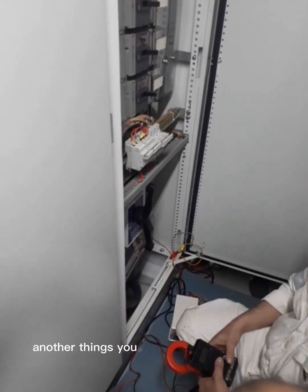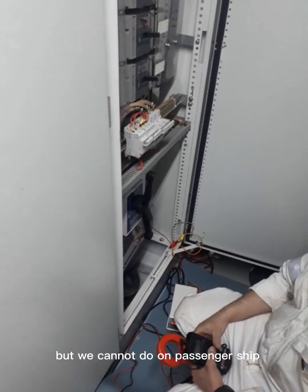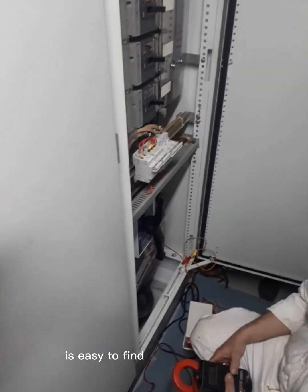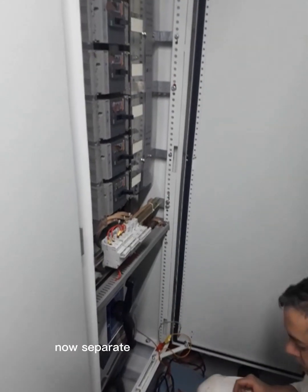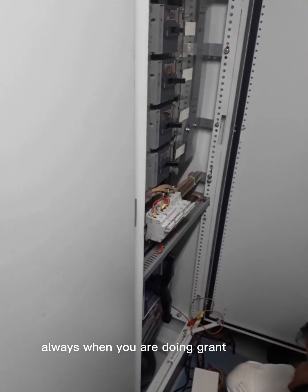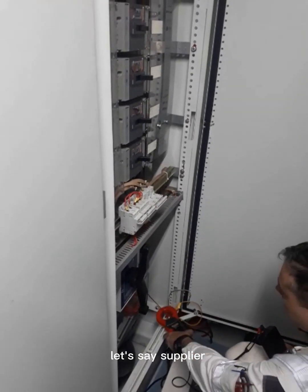And other things you need to switch off, switch by switch, but we cannot do that on a passenger ship. So that's what Timo says, it's easy to find which one it is. You go by the number and you go up and you know now separate breaker by breaker, if possible. Always when you are doing ground fault finding, read what is right for what, because some of the suppliers we cannot shut down.